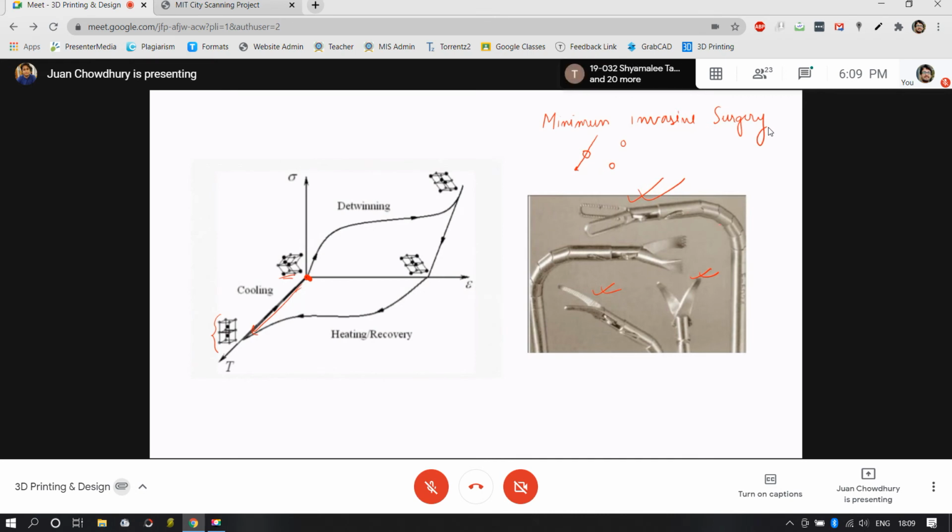As they pass, each section of this arm is actually made out of this nitinol alloy, and within it go the control heating elements to each of the connections, and based upon that you can make the movement of the system. Okay, and the complexities of these structures can now be made with 3D printed nitinol systems.